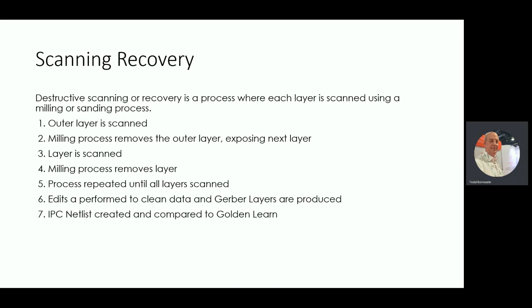And then from there, we go back and, or what I should say is, we go through and check all of the layers to make sure that all the traces are good, and we can bump them up to size. If they want a certain trace and space criteria, we can bump the traces up, we can take them down. If we see any violations, we can make adjustments to connections, to holes and pads and vias.